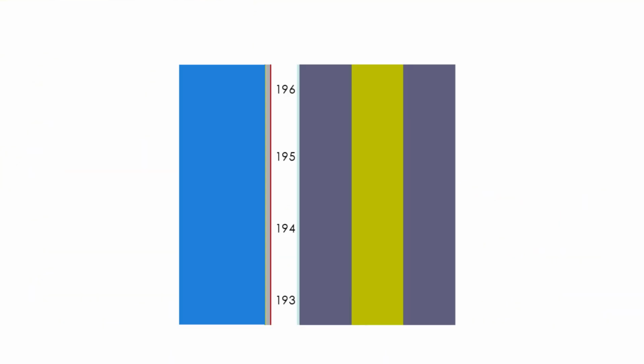To obtain a more detailed temperature distribution inside the cavity, we will subdivide it into 4 parts. This approach creates 4 separate convective nodes, allowing the airflow to pass from one node to the next. This provides a more precise temperature profile along the cavity height.